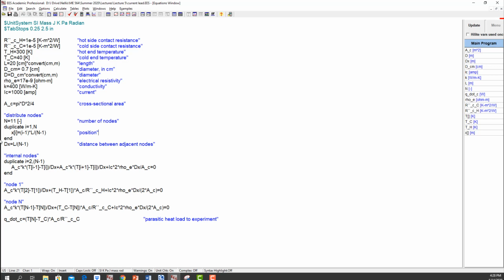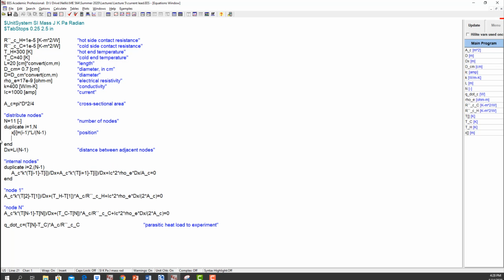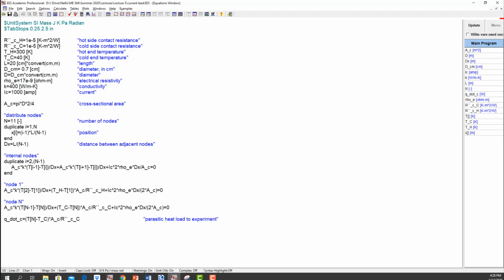It's not like MATLAB or a formal programming language that uses assignments. If I was using assignments, this would be no problem. I would just sort of move through this. I'd make this assignment, I'd make this assignment, I'd make this assignment again, and I try to make this assignment again, and that'd be fine, right? This is kind of a stupid thing to do, to reassign a over and over again, but it wouldn't cause you an error, right? It would be fine. It's going to cause me an error if I do this in EES.